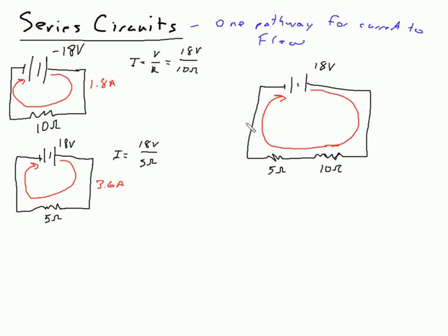And so in doing this in the lab here, we've measured already that this was 1.2 amperes worth of current. We measured it here, measured here in between the bulbs, and also got 1.2 amperes of current. Measured over here and got 1.2 amperes of current. So we find in this process that we have the same current everywhere.